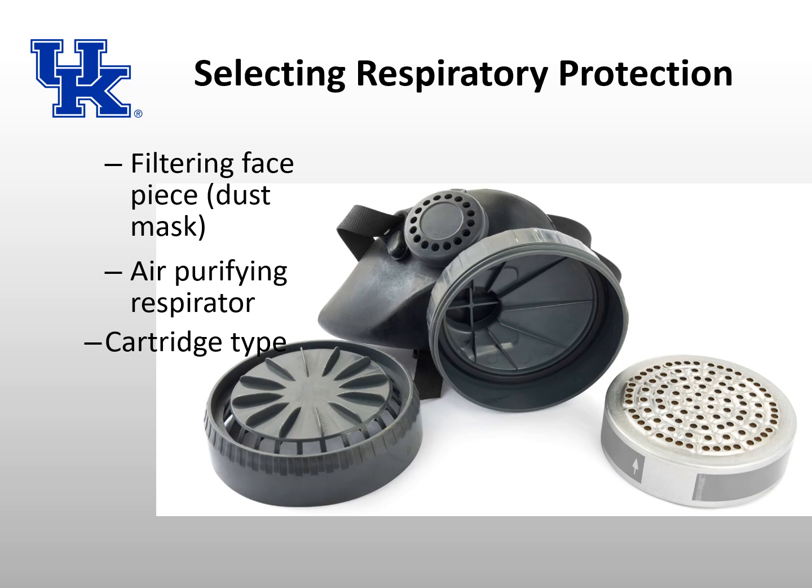Cartridges for air purifying respirators are carefully chosen by your employer. No type of cartridge will filter out all possible contaminants, so the cartridge will be specific to the hazard. In addition, it is important to know how long it takes for each hazardous material to break through the cartridge. This lets you know how often the cartridge must be replaced.